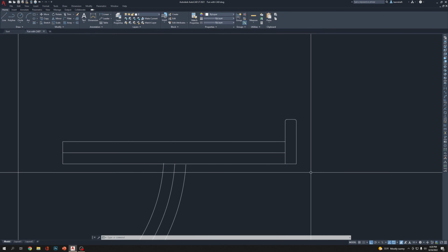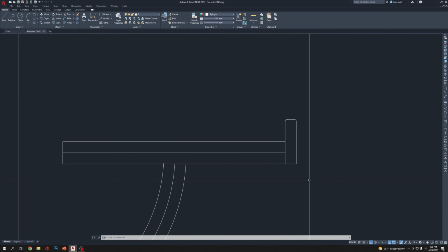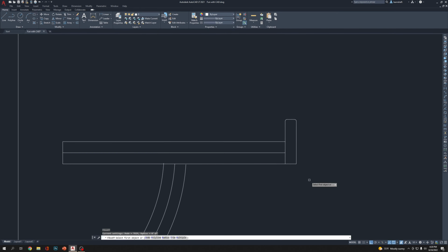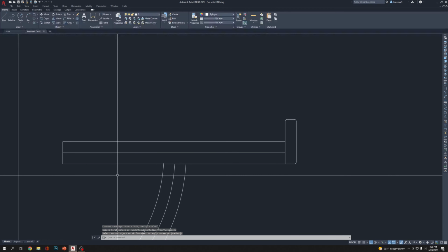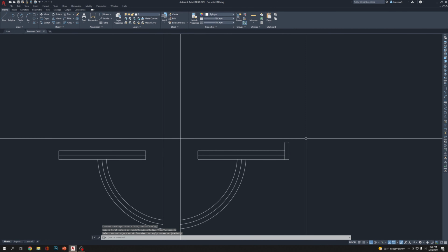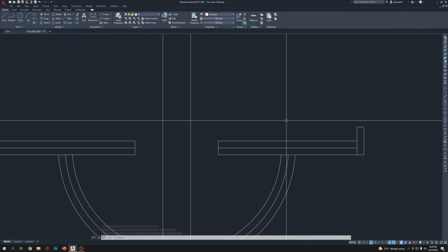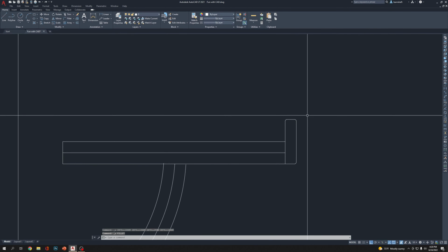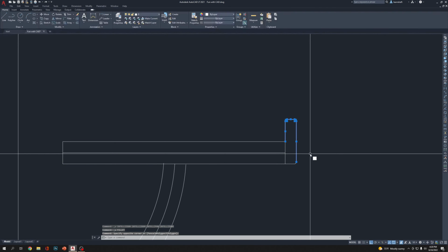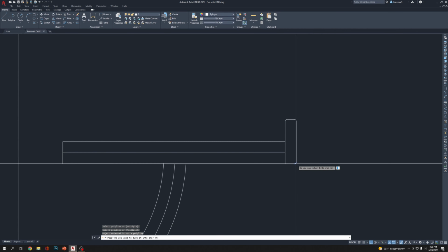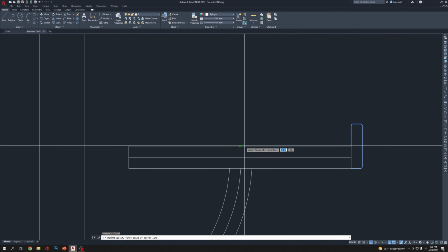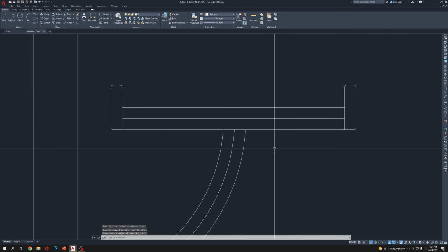Now you may ask, what about this corner? Can I make it? Yes. Fillet, enter. Make this corner also a little round, so people are not going to get hurt. Oops, I did this one too. Okay, Control C. So select this one, PE, enter. This line, enter, join. Select as many lines as you have, enter, it becomes one piece. Mirror it from the center, click, enter.